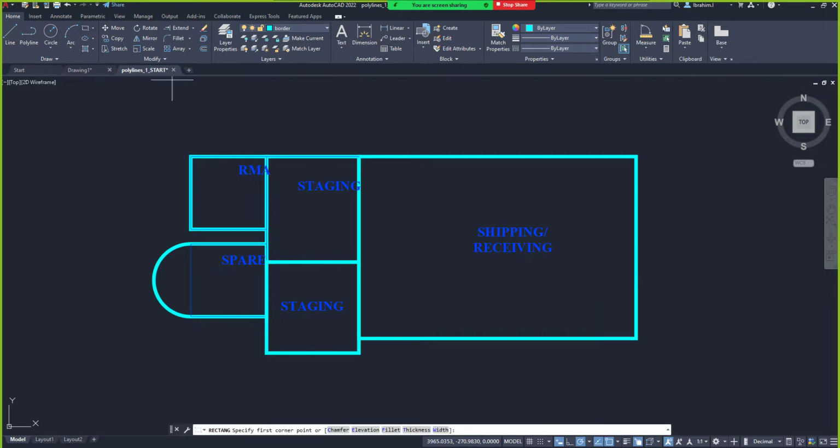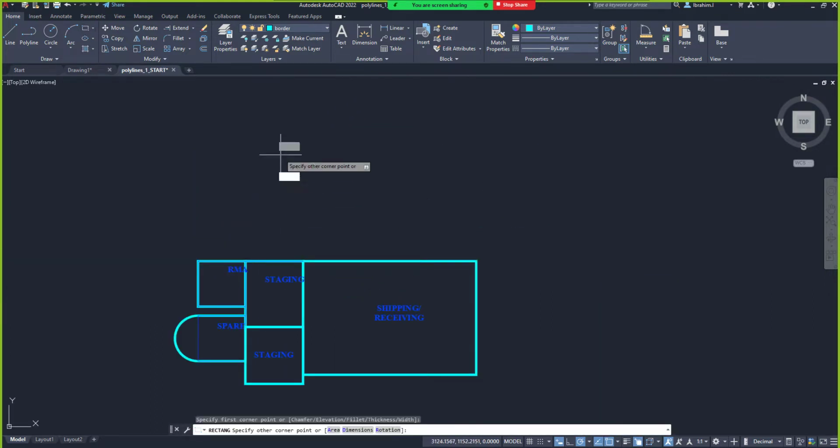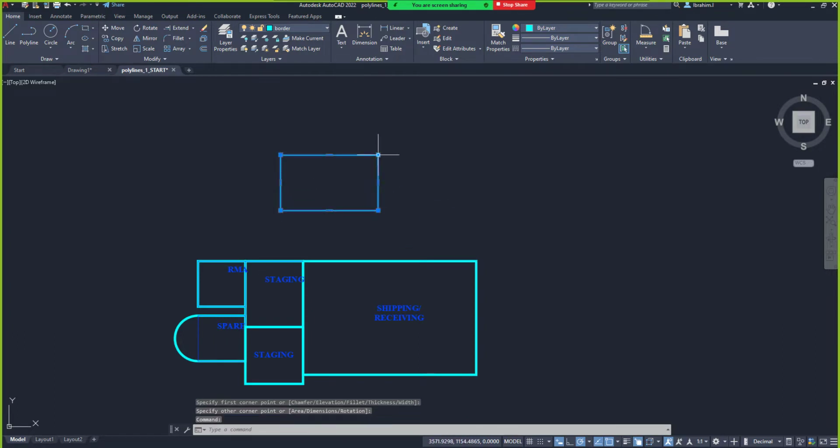When I create a rectangle and select my rectangle, can you see we have different nodes around this object? We have different node points around this object. They are known as vertex points. Can you see that? When I'm not clicking, I'm just moving my mouse and I place it at one of the vertex points here. Can you see it's showing me stretch vertex? It's showing me add vertex. It's showing me remove vertex. If I click on remove vertex, it removes that vertex.